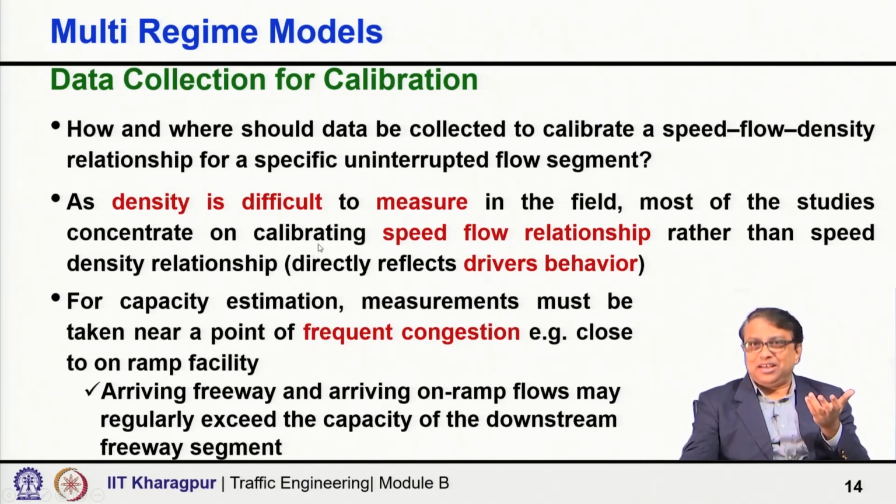Generally, as I said earlier a number of times, density is difficult to measure directly in the field. So, most studies attempt to calibrate the speed-flow relationship rather than the speed-density relationship, although there is a much deeper sense in the speed-density relationship, because it directly reflects driver behavior.